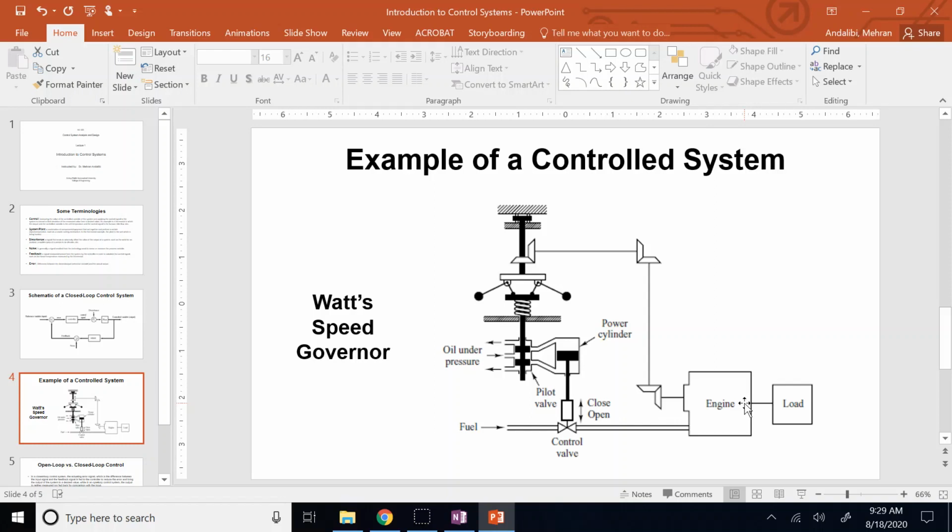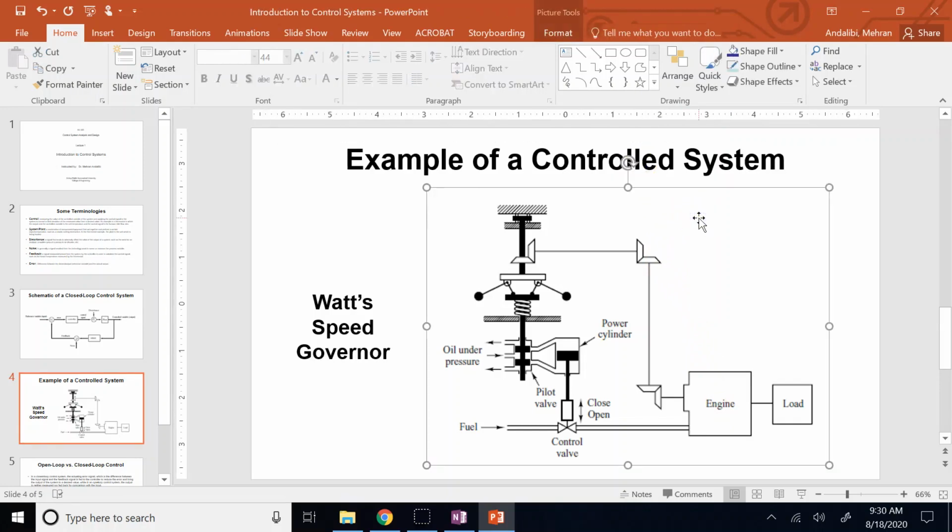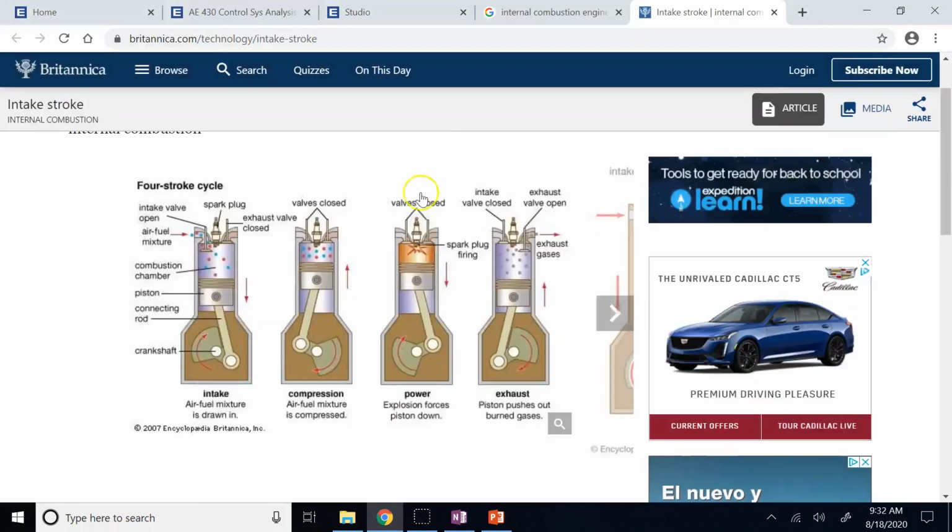Now you close the exhaust valve and open the inlet valves. Now what happens? Yes, since you have a very low pressure region or a relative vacuum inside the cylinder, that causes the fuel to flow into the engine. Good. So that's the mechanism for bringing in the fuel, or at least that's what it used to be in basically older engines, the ones that did not have an injector, the ones that had a carburetor.